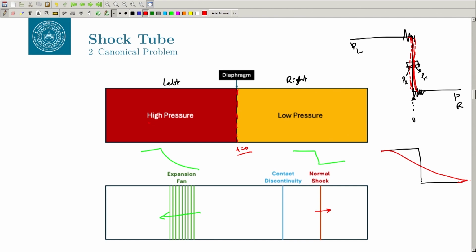What we rather want to see is, even if there is a discontinuity, this discontinuity is very small, and the scheme should be able to predict it like this. We want a scheme which predicts like the blue line, and if it can go better than this, that is better, and not the red line. The red line is not a good prediction. Although it is more stable because of the added dissipation, it will give you a result, but it may be very smeared out.